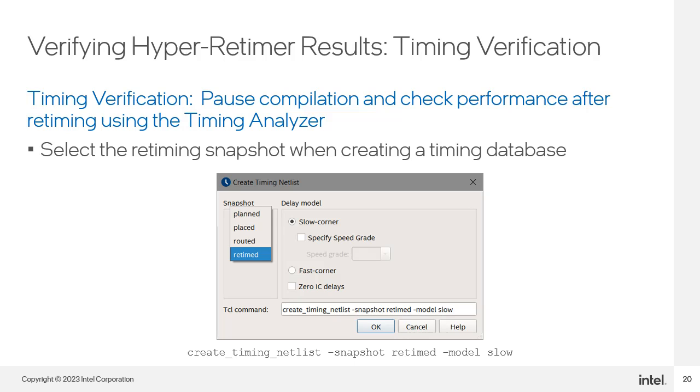From there, you can generate all of your typical timing analyzer reports to do the actual analysis. Be aware that the compiler's final stage has yet to run, so the software has not made any attempt to fix potential hold time issues.